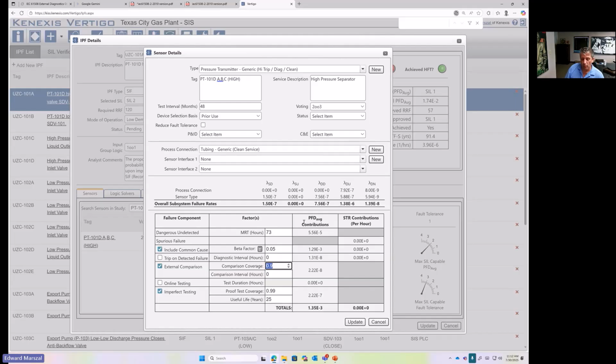Now, if a 1% change, or let me say a 1 foot change in level in your vessel, means that one transmitter changes by 1 milliamp but the other transmitter changes by 2 milliamps, it's not that you can't do a comparison of those, but your comparison got stupid complicated, because in the code that you write to compare the signals, you need to put in a factor that says this transmitter needs to be moving twice as fast as the other transmitter. So I'm not going to tell you that it's impossible to do it, but doing it is really complicated because